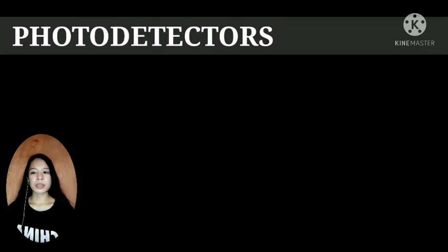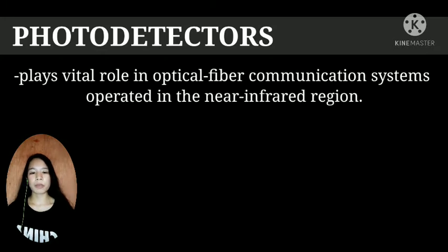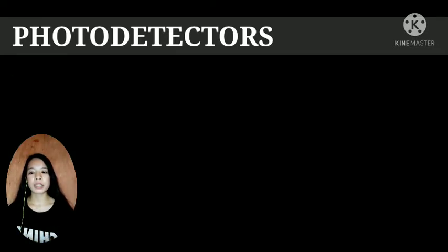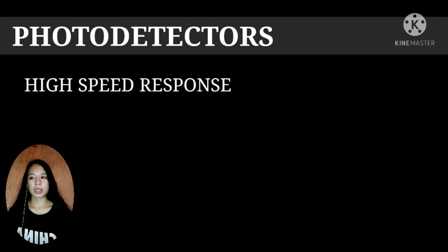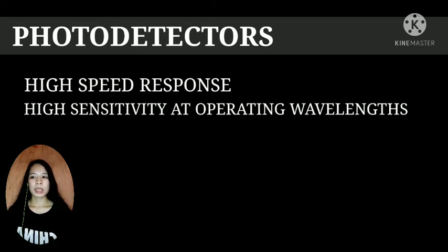So photodetectors play a vital role in optical fiber communication systems operated in the near-infrared region. They modulate optical signals or convert the optical variation into electrical variations, so that they are subsequently amplified and further processed for the application. Stringent requirements that are met by the photodetectors include high-speed response, high sensitivity at operating wavelengths, and minimum noise.